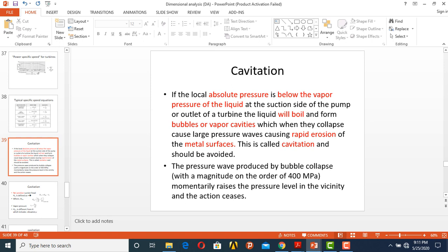So that rapid vapor cavities, the jets that come from those bubbles will go and bang against the walls of the pipes. That's why cavitation is important in any design, especially where fluid flow is concerned. Whether it be a water utility company, an underground water line, or the normal flow of things, cavitation has to be taken care of first from a design point of view.